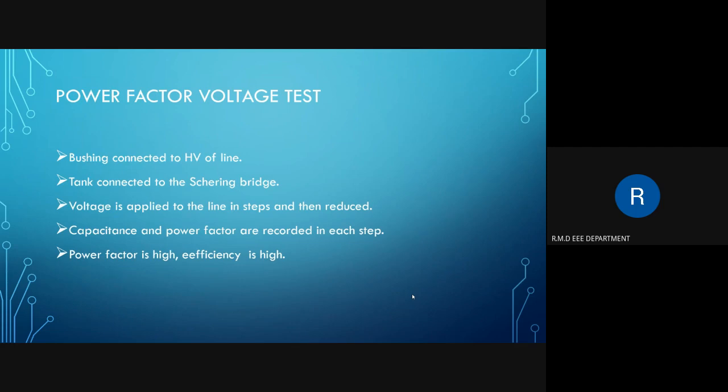In the power factor voltage test, the bushings are connected to the high voltage side of the line and are immersed in the oil. The tank or earth is connected to the detector side of high voltage. Here we are using a Schering bridge, so the tank is connected to the Schering bridge. The line voltage is applied in steps and then it is reduced. The capacitance and power factor are recorded at each step. If the power factor is low, the efficiency of the bushing is high and it has a long life. This is the power factor voltage test.